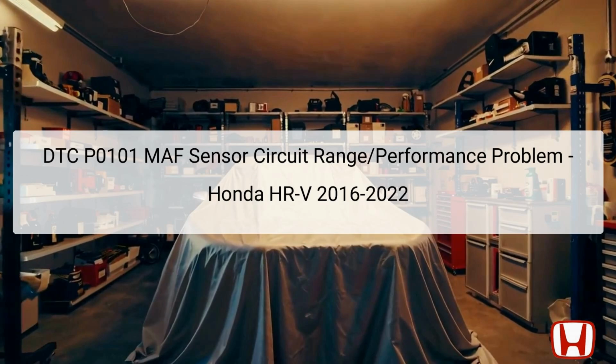The diagnostic trouble code DTC P0101 indicates a problem with the mass airflow MAF sensor circuit, specifically indicating a range or performance issue. This diagnostic code is crucial for maintaining optimal engine performance as the MAF sensor measures the amount of air entering the engine, which the Engine Control Unit, ECU, uses to calculate the appropriate fuel injection and ignition timing. If the MAF sensor is not functioning correctly, it can lead to reduced engine performance, increased emissions, and potentially damage to other engine components.